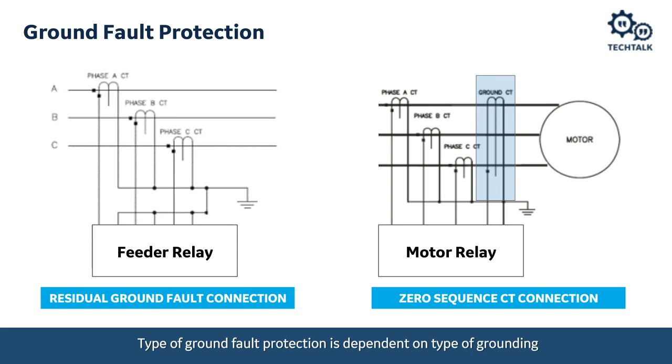Well, we know that the C37 guides that describe how we build and model CTs say that when we're in the linear portion of its excitation curve, we could have as much as 10% error.